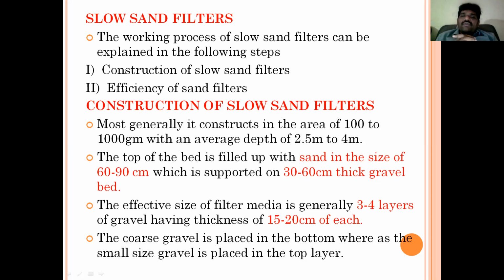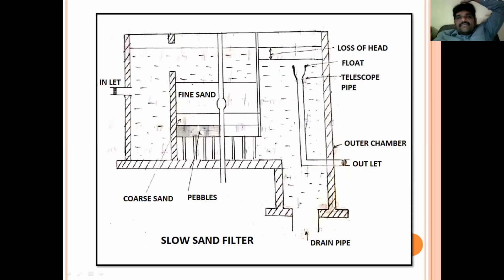The top of the bed is filled up with sand of 60 to 90 centimeters, which is supported on a 30 to 60 centimeters thick gravel bed.